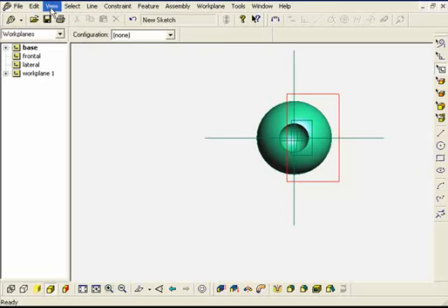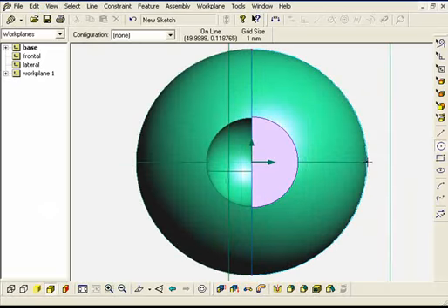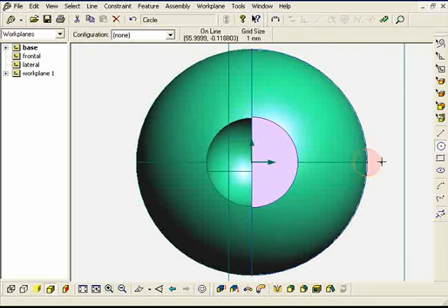Select the View on the Work Plane tool and select View Auto Scale. This time draw a small circle whose centre sits on the outer edge of the hemisphere, of diameter 12 mm.